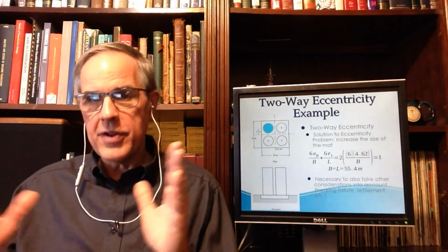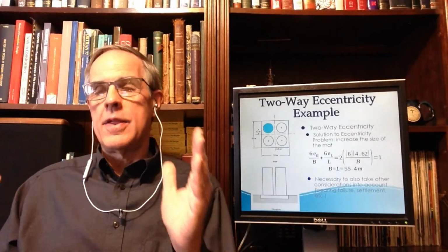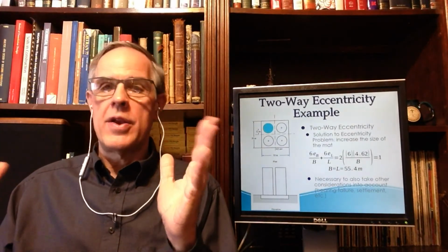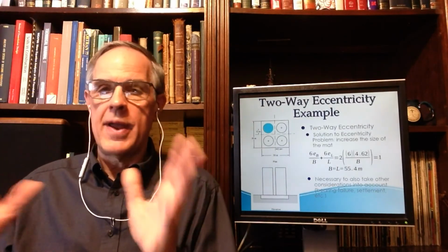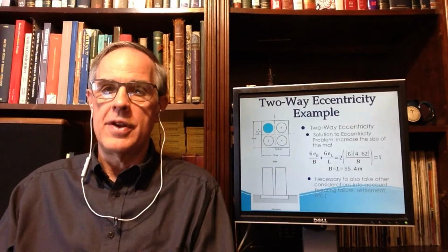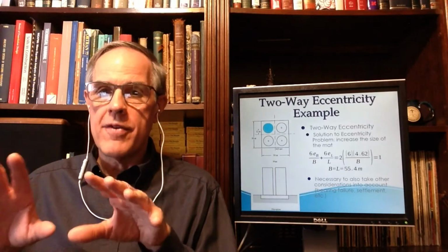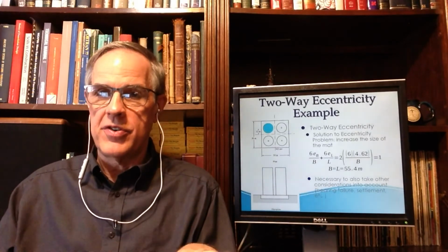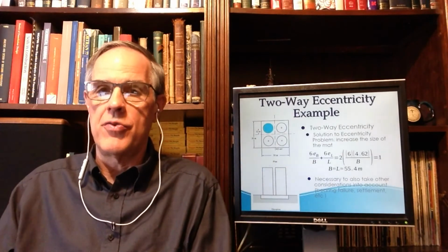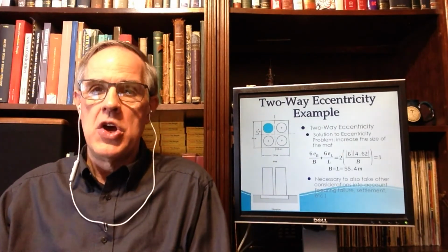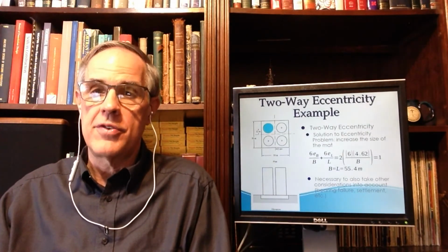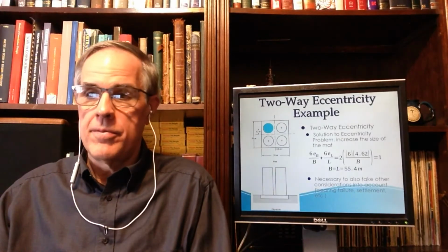As I increase the mat, the weight increases, which would actually lower my eccentricity. Generally speaking, the weight of a mat, most of which are concentric in their configuration, or the weight of a footing, will generally tend to decrease the eccentricity of the load.